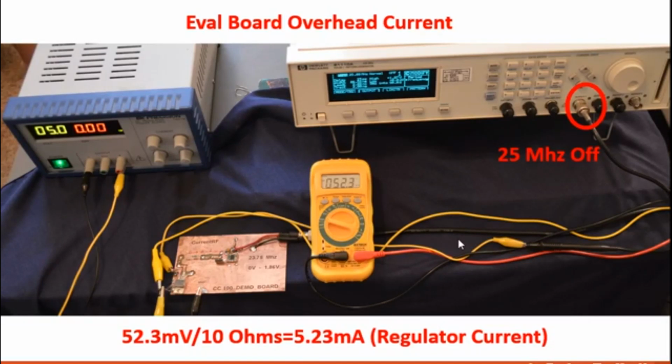This is a small-scale mock-up of an AI processor. If you'll notice, we wound up with about 5.23 milliamps of bias current. You typically can't really get away from that. You have to have something in the part to bias it up. The only way to reduce that is to actually redesign the part for lower biasing currents.